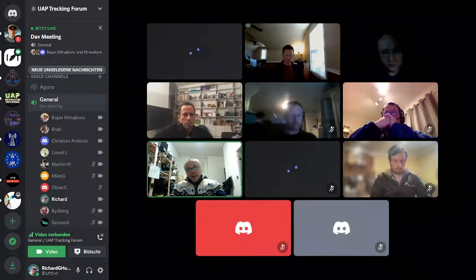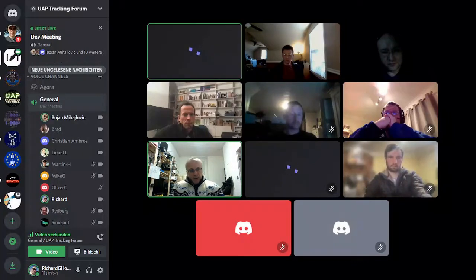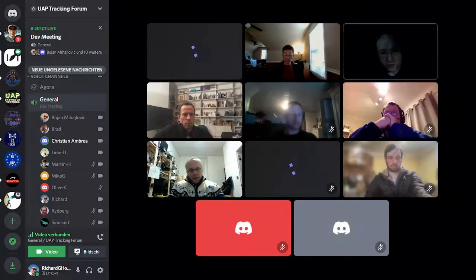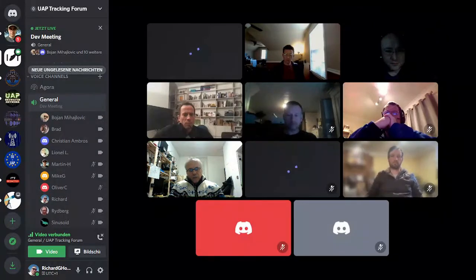And you say the buffer of the Nano is too small, no matter what library you're using, or it only is capable of 2 megapixel video streams with a frame rate of 30 frames per second? Yes. It can use a 12 megapixel camera like the IMX226, but then the frame rate is down to 1 frame per second. Okay.